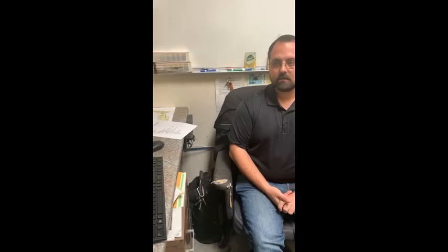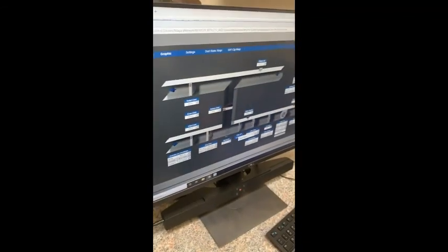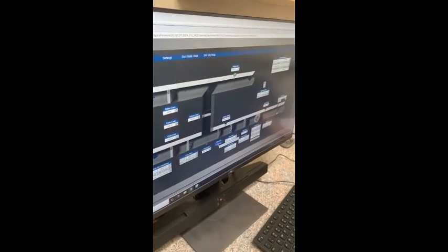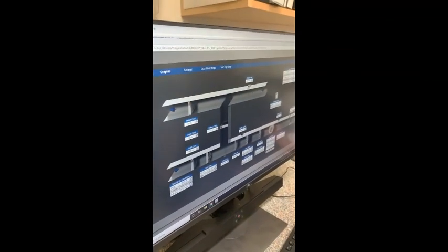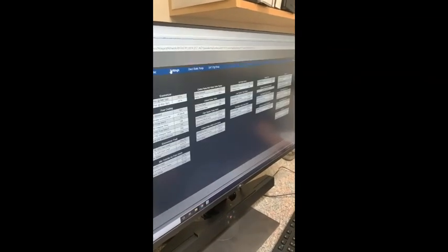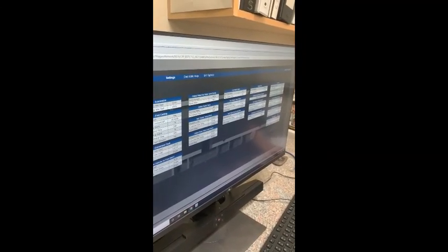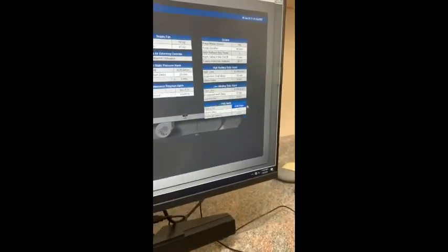There are high and low static pressure safety switches. There's a filter DP. Is that shown right there? Yes, right here. If it goes into alarm, where do you reset that alarm? It will show here like a flashing red. It will show up in that alarm console as a filter alarm. What is the alarm set at, is what I mean. Yeah. So right now it's set for 0.08 inches of static.